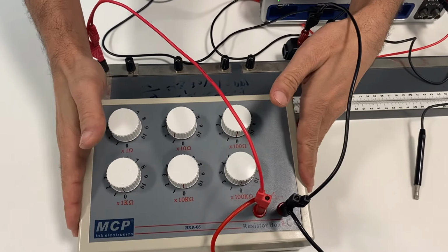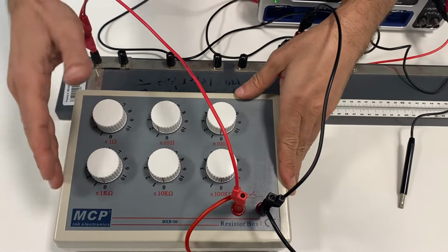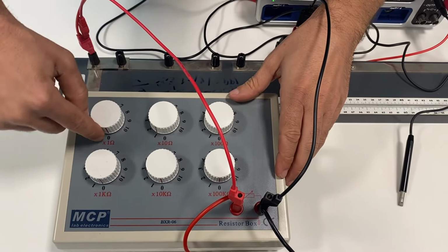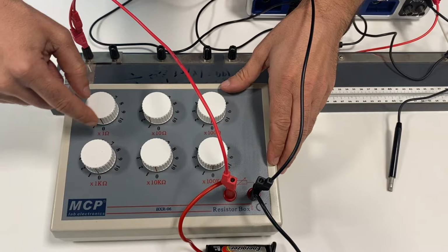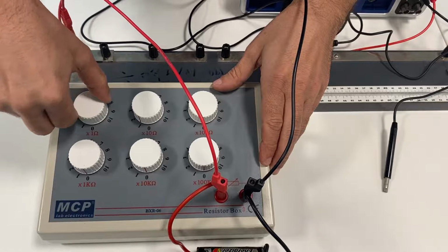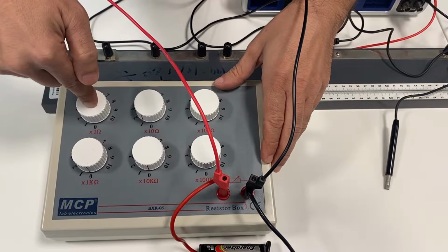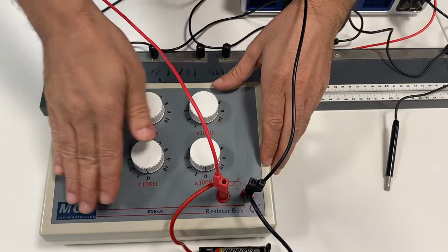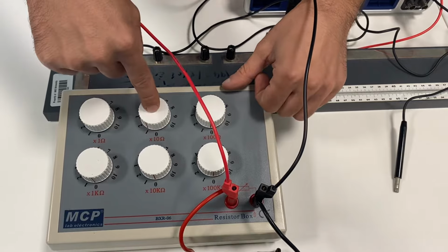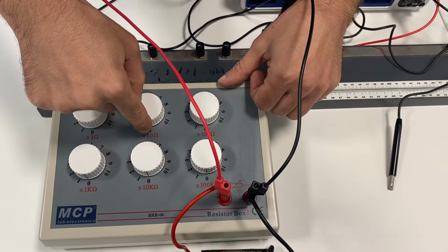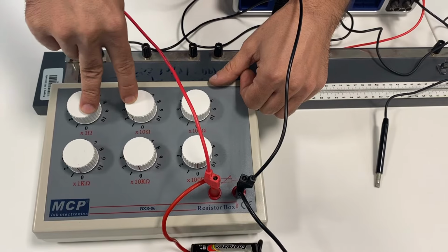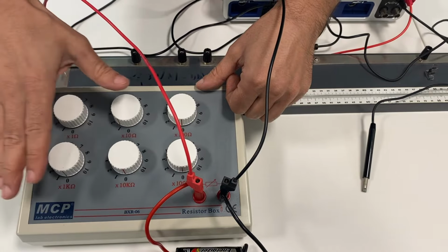Now this is the resistance box and it is very important to learn how to use it before you start the experiment because you have to do your experiment quickly. Now this knob here has times 1 ohm beneath it, which means that these numbers represent how many ohms you have. So for example, if I set this to 5 times 1, that's 5 ohms. Now, this is correct provided everything else is set to 0. Now, if I have the second knob set to 1, 1 times 10 is 10. So 10 plus 5, we have a total of 15 ohms, and so on. So all the contributions of these knobs add up like this.